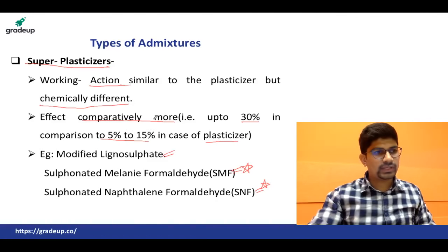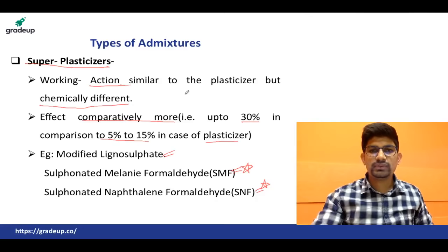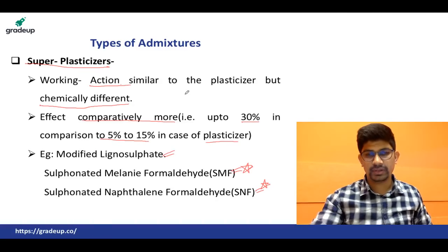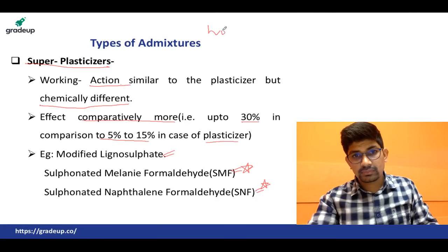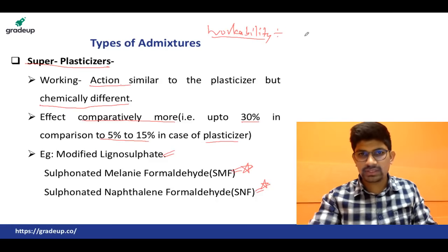Someone is asking about the workability. Workability is the ease with which concrete can be mixed, transported, placed, compacted and finished. Suppose you are constructing a multi-storied building.